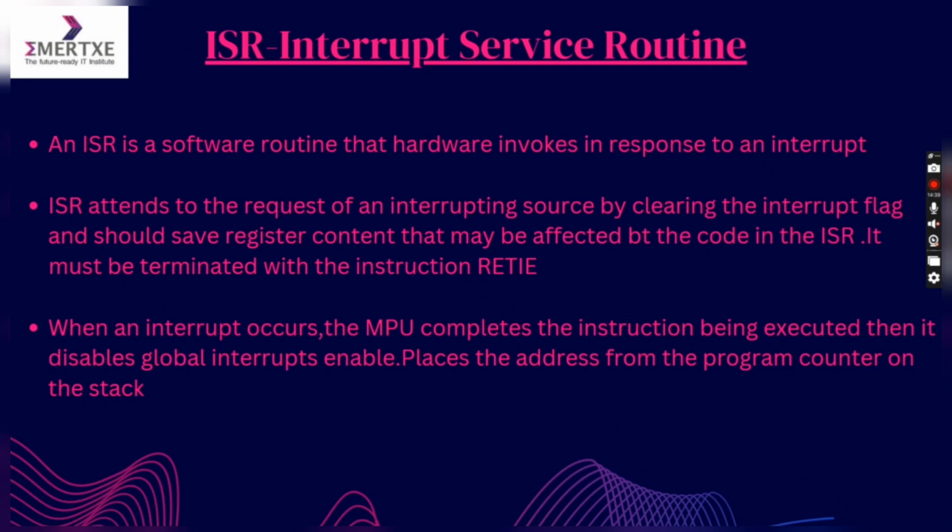It then pushes the address from the program counter onto the stack. This process ensures that once the ISR has finished executing, the microcontroller can return to where it left off in the main program. The ISR attends to the request of the interrupting source by clearing the interrupt flag. It's important that the ISR saves any register contents that may be affected by the code in the ISR. This is to ensure that any ongoing operations are not disrupted.